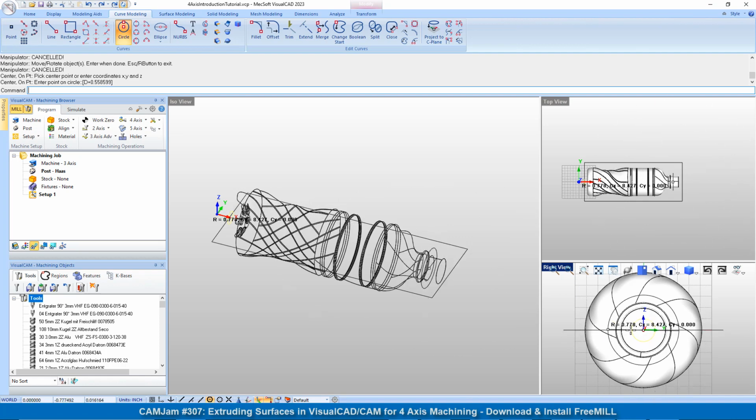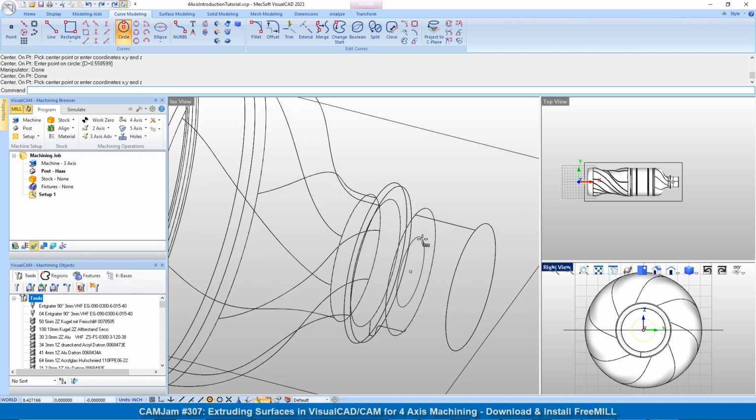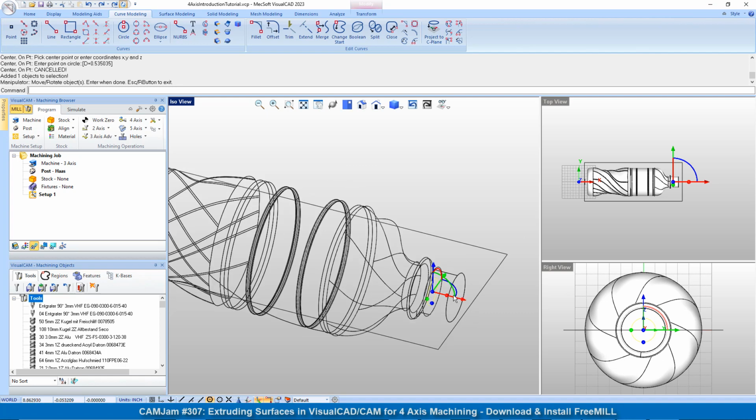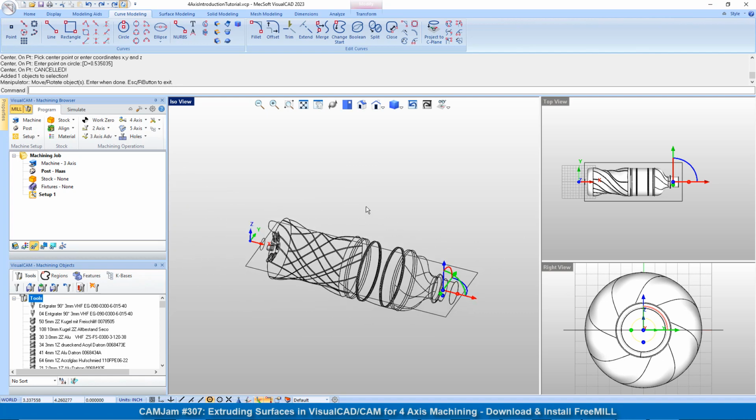So we're going to go ahead and just drag it. It doesn't have to be exact as long as it's less in diameter than this perimeter here, this diameter. So we're just going to drag it out and put it right there. So you'll see that it was located right here. Escape, select that. So there's our circle. There's actually another one down here, let's delete that for now. So let's move this circle down to the origin before we extrude it, okay?